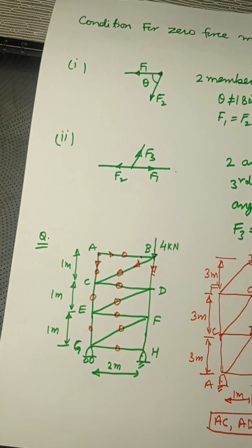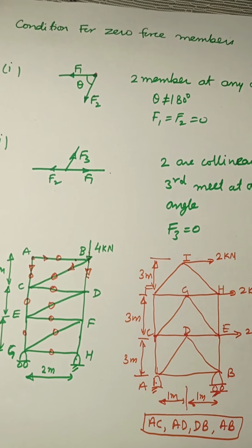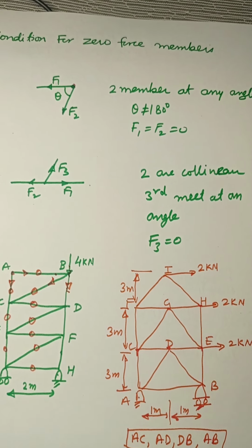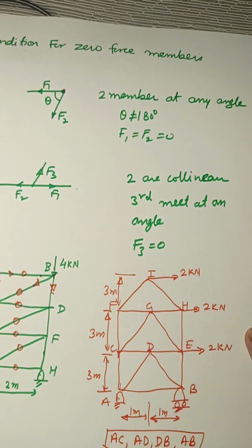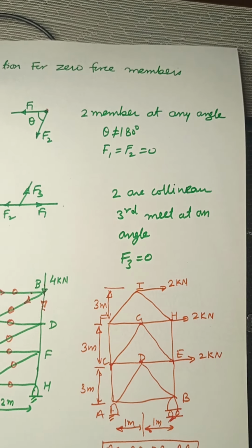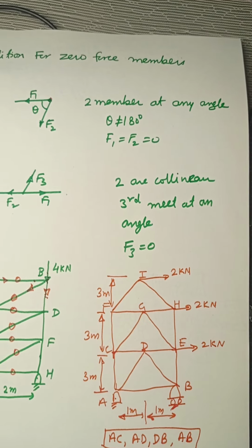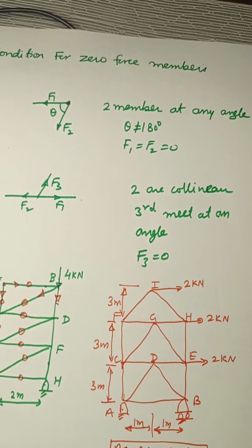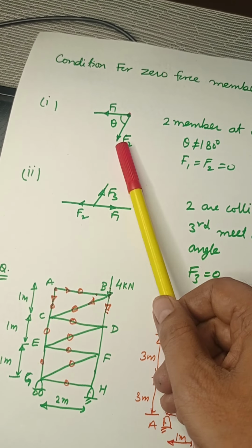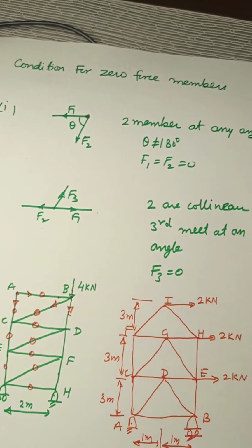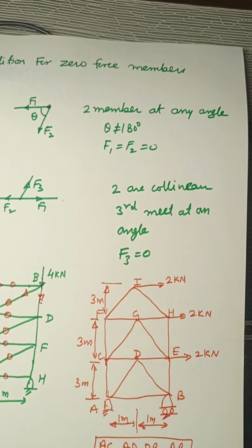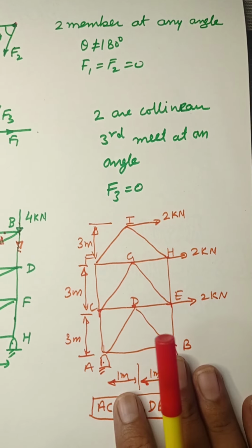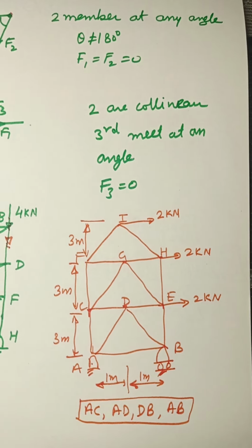So this kind of question can be there in competitive examinations, and even in some complicated questions, one or two members can be 0. So try to see this whenever you are doing any question. If anything is becoming 0, write it 0 before starting the question and move ahead using these two concepts. You can straightforwardly write this and proceed. If you are getting 0, you can write that this is 0 because of this reason. Now another typical question I am giving you, where you have to cut more than three members.